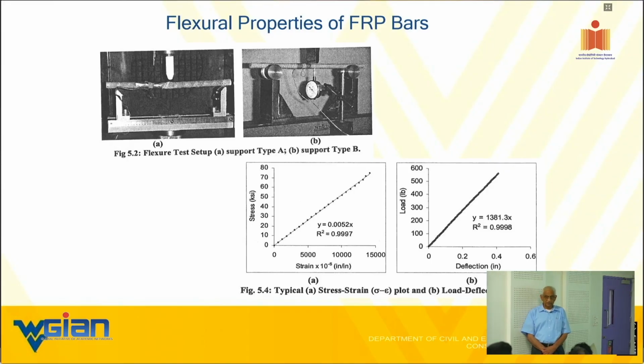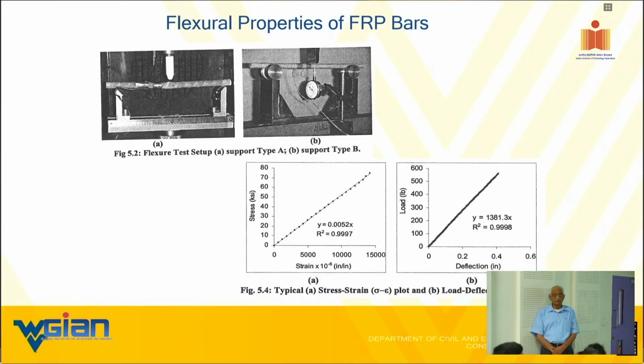Local compression. So keep those 4 in mind. Never ever conduct a bending test below 12 or above 40. Keep it somewhere in the mid zone, 20 to 24, or else your results can be skewed.